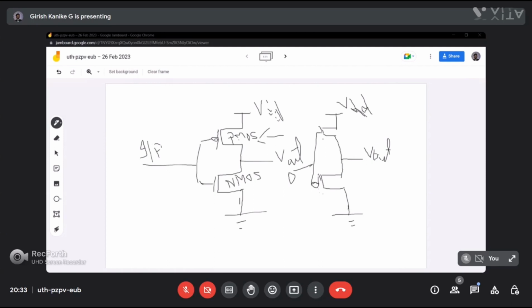No. Praveen, are you sure about your answer? If PMOS passes perfect 0, what does your circuit 1 act as? Sir, circuit 1 acts like an inverter only, sir, but the second circuit acts like a buffer, sir. Okay. Why? Because PMOS passes perfect 0. Yes, sir.